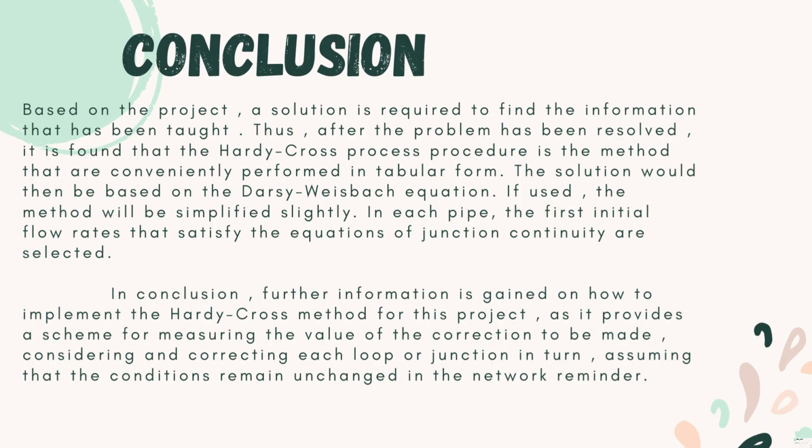Next, for the conclusion, based on the project, a solution is required to find the information that has been taught. Thus, after the problem has been resolved, it is found that the Hardy-Cross procedure is a method that is conveniently performed in tabular form. The solution would then be based on the Darcy-Weisbach equation. If used, the method will be simplified slightly. In each pipe, the first initial flow rates that satisfy the equation of junction continuity are selected.